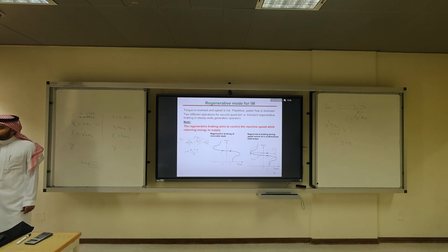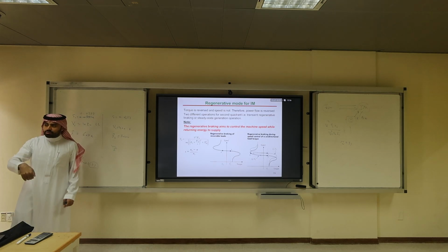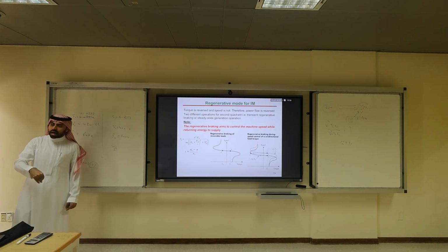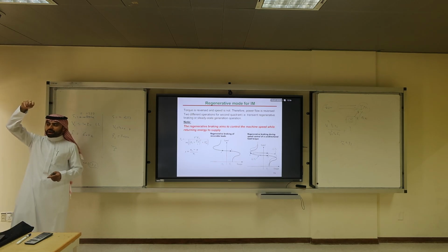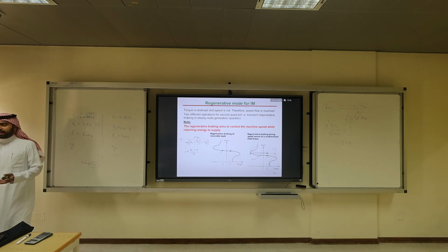The forces of the load, the free body diagram, always down. The elevator will not go up and then down. It's always down. Now, if you want to push it down, you go in the favor of it. If you wanted to pull it up, you apply opposite torque. This is on the motor side. So I can say it's unidirectional. It's not active.